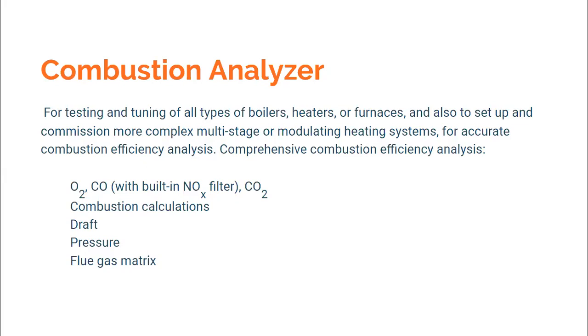So what are the things we are interested in? With the combustion analyzer, we are interested in knowing the oxygen content in the products of combustion. The combustion analyzer will tell you how much oxygen is present in the products of combustion. Now, why is oxygen present in the products of combustion? Oxygen, as you all know, is used for combustion, and not all of the oxygen is utilized in combustion. So some of the oxygen will come in the flue gases, and the oxygen present in the flue gases will give you a fairly good idea about how much air is being supplied for combustion.